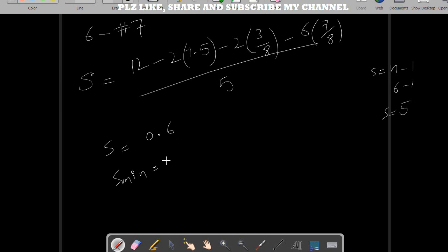Now if I compare this 0.6 with the minimum criteria, which is S minimum, which is the diameter of the bar, and the diameter of the bar is 7 divided by 8, so I got 0.875. So this time we see here that S is not greater than S minimum, so not okay.